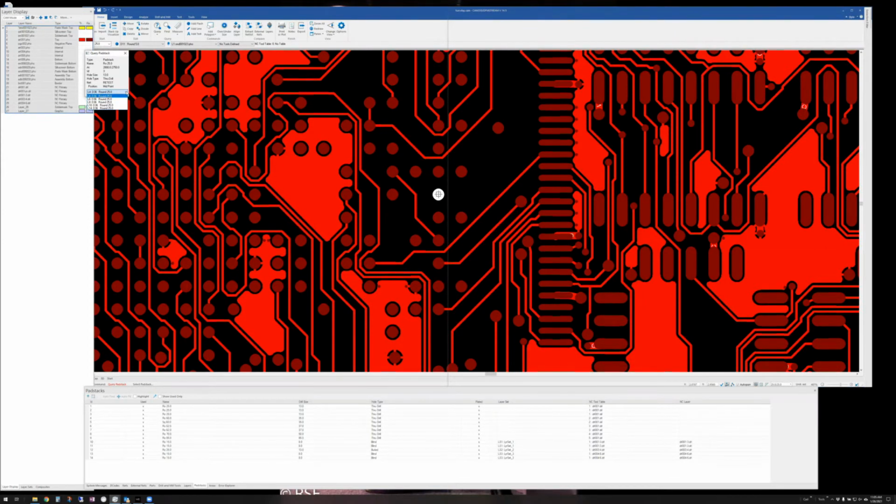So I would probably just stay away from using those, and you can even turn it off if you want to down here in the tool. Now, one of the things it does is it sets the hole types based off of the technology of that particular pad stack. So you can see it made some of them blind and some of them buried. And if you have the higher end analysis, it'll pull that forward and use that for running the analysis. But for the 160, I don't know that you would ever really care about pad stacks.